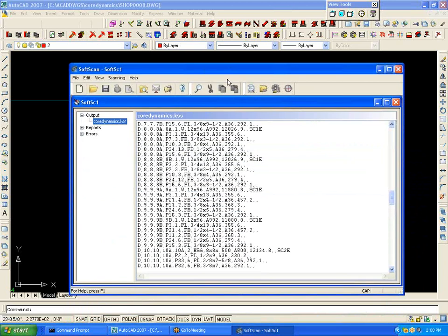This file, with one click of the mouse, will import into FabTrol and totally eliminates the tedious task of typing all the bills of material into FabTrol, Fabsuite, EJE, ROMAC, Steel 2000, or whatever MIS program you're using. In addition, we'll do an integrity check of the bill of material. We'll look for missing information that's required, such as the quantity, the length, the description, and so on. If you have a piece marked P1 on sheet 1 and have it again on sheet 3 and it's different, we'll flag you the fact that it's not standard for the project.